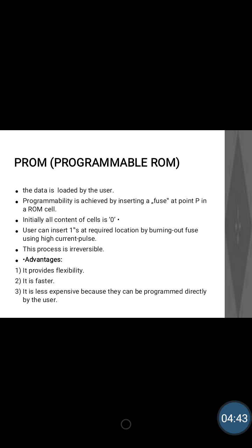This is an irreversible process because we have burned the fuse and we can't insert one more fuse again. That's why it is only programmable, it's not erasable. It is programmable only once, and that is done by the user. Some of the advantages of PROM are that it provides flexibility, it is faster, and it is less expensive because programming can be done by the user directly.